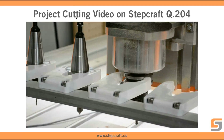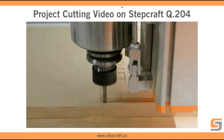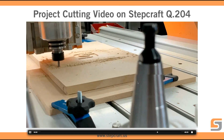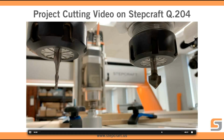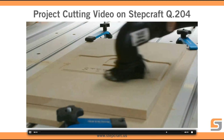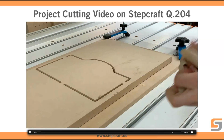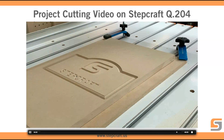And when the spindle starts back up again, the air cylinder releases, and you can see here it's in the down position. So now the dust boot stays in constant contact with the material. The other nice thing is it's not pneumatically pushed down. It uses gravity to push it down. So what that means is that the dust boot always stays in contact with the surface despite the height of the Z-axis. So if you're doing a carving job that has a lot of Z-axis movements, the dust boot always makes contact. So it keeps the work area much cleaner.